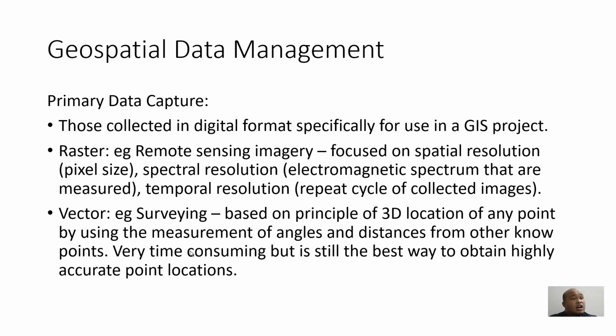Primary data capture are those collected in digital formats specifically for use in a GIS project. So the key point right here is directly in a digital format. So once you capture the data, let's say you are using surveying work or you are using GPS, you plot that particular position. Let's say the one point that we have been talking about, right? So the system will take that one point digitally, right? So that is the primary data capture.